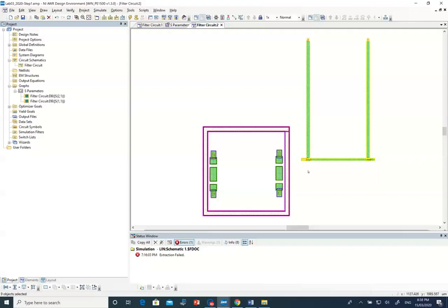Now a few things to note. This is called the frame, and this is called the RF pads. This is the RF in pad where the signal comes to this point, and these two points are called ground. You'll notice this is a via. A via is something that connects your ground pad to the bottom ground pad. This is a top view, so normally it's ground, signal, ground.